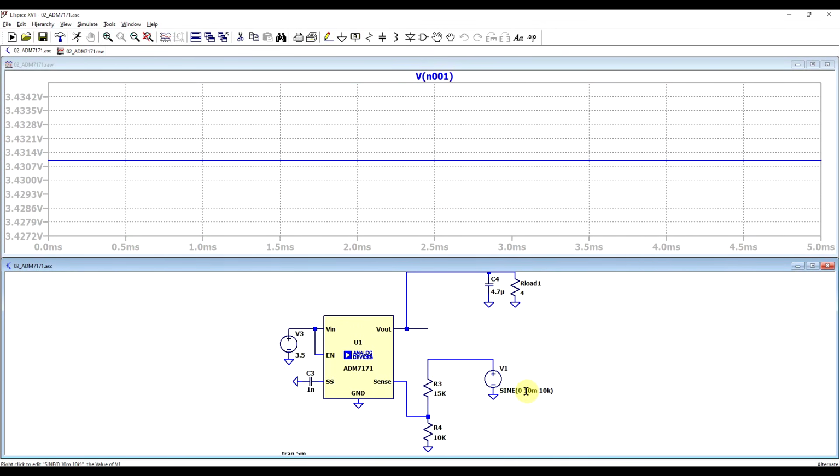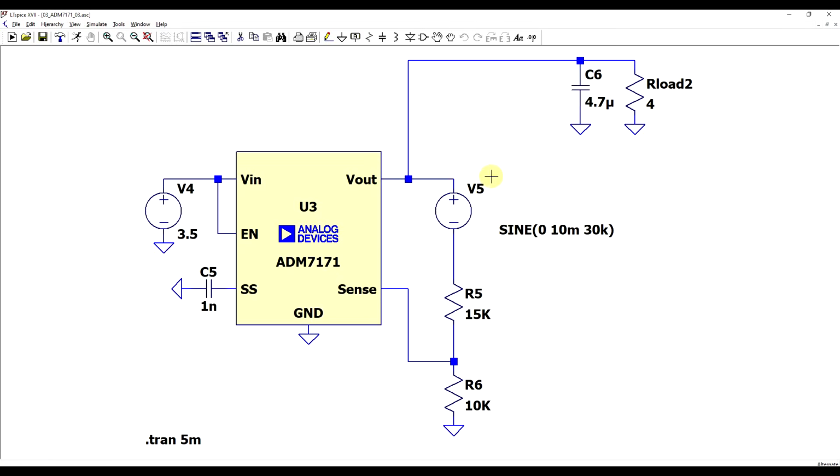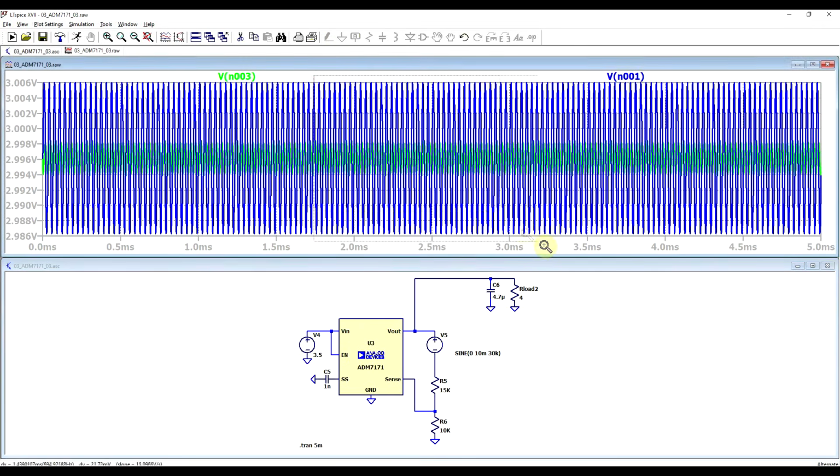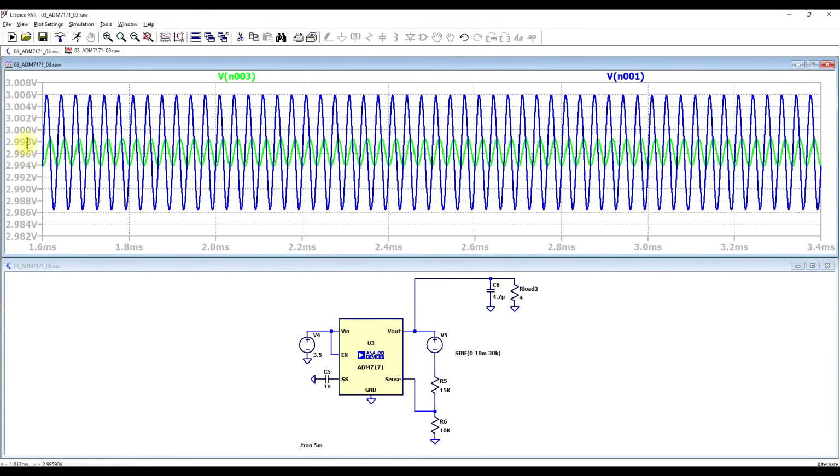Now, even if you could stabilize the loop, the other problem is that you need to keep strict control on the output. So especially at low frequencies where you have a lot of gain, you will need to inject very small signals. So the way around this is to inject the test signal into the loop directly without completely interrupting it. So to have the signal source connected into the loop interruption. This way, we can monitor the injected signal, but also the output response, which is centered around the 3 volts